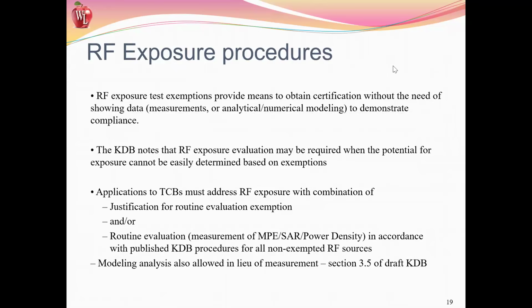RF exposure test exemptions provide a means to get certification without the need to show any measurements or analytical numerical modeling to demonstrate compliance. The KDB notes that the RF exposure evaluation may be required when the potential for exposure cannot be easily determined based on exemptions. Again, you've got to make sure you cover the worst case.